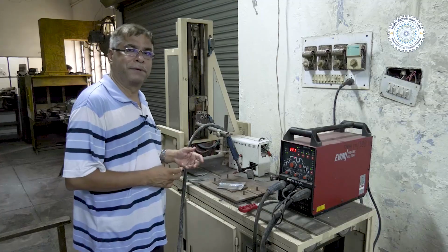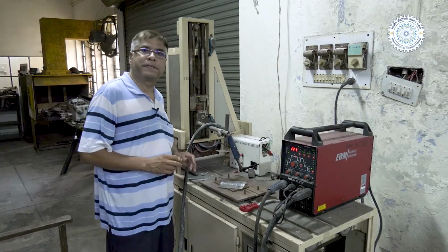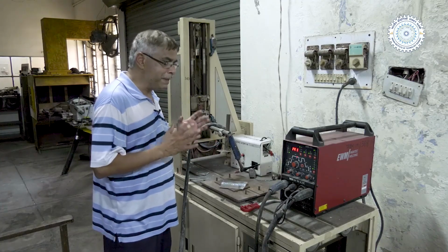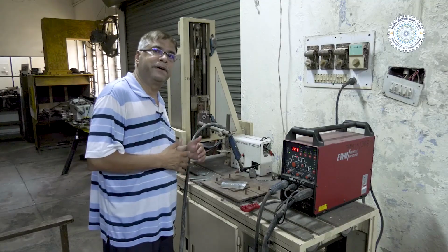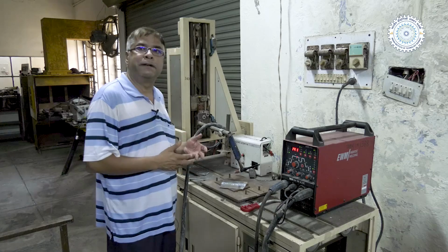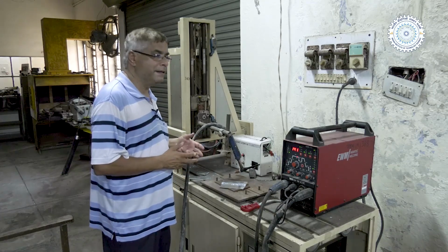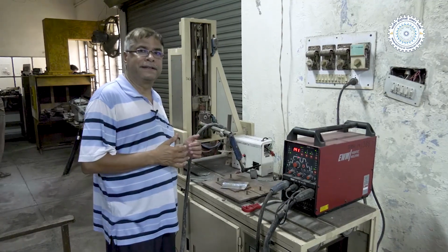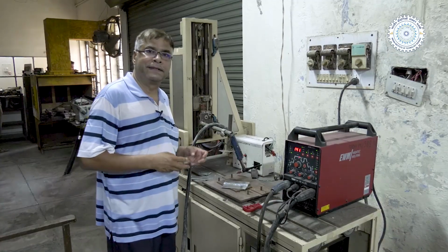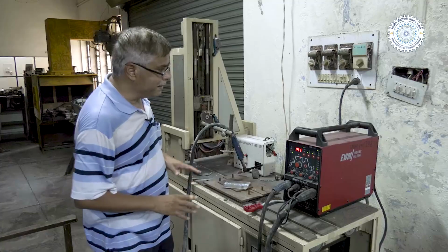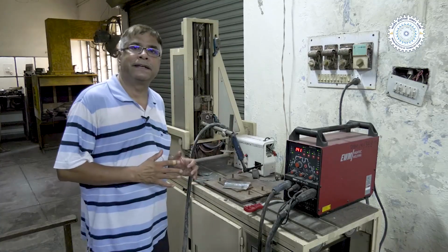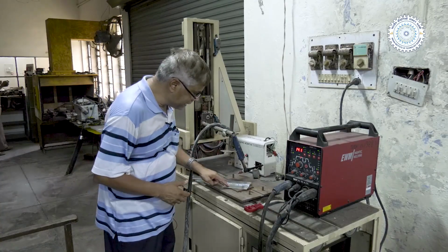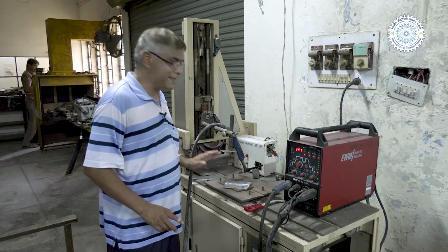among the other arc welding processes, because it is a very low heat input process. It helps to establish the arc using very low heat input, and the application of inert gas like helium or argon for protecting the weld pool during welding, coupled with a very small arc length, allows the cleanest weld in terms of oxygen and nitrogen content in the weld metal. Here you can see TIG welding is based on the principle of using the arc heat developed between the base metal and the non-consumable tungsten electrode.